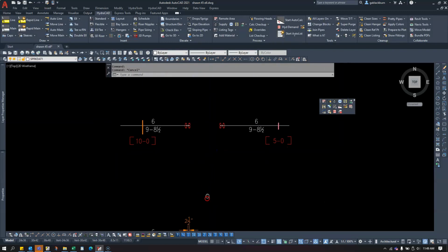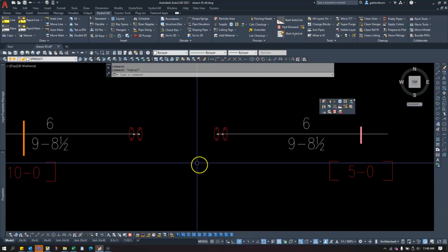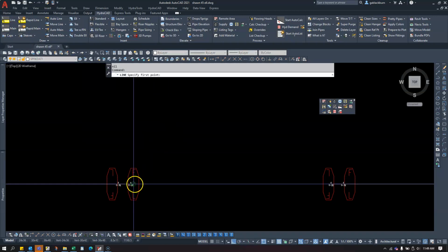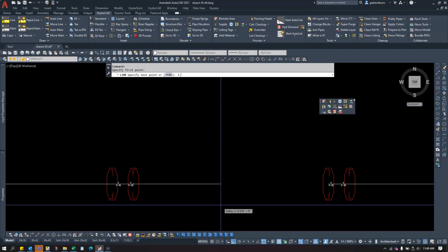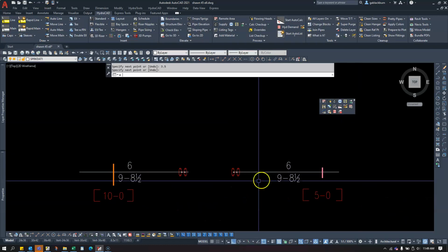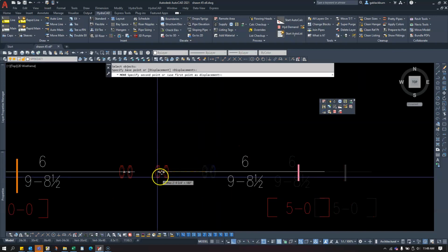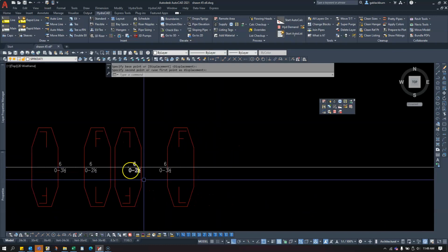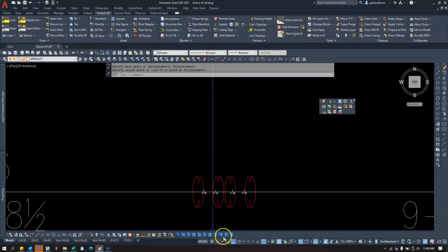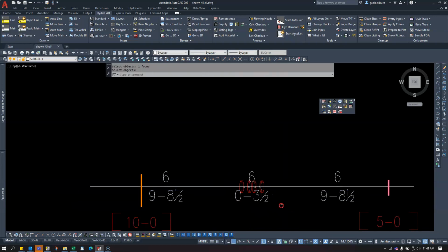The other thing I want to do now is draw a pipe that's 3.5 inches long to ensure that I have my spool piece in here. So I'm going to go from here and 3.5, enter. I'll move this whole section over, so move all of this from this endpoint to this endpoint. So unfortunately, this is the way we have to do it because we're doing everything in 2D. So we're just kind of stuck with it. So just kind of keep that in mind. Okay, so now that's 3.5 inches.